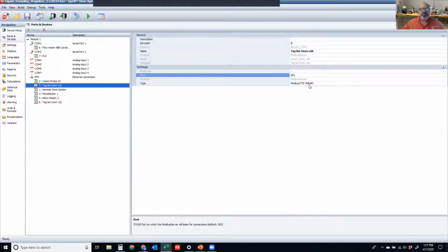So it's a way of creating multiple communication templates that are used within Ethernet and serial that allow the FlowX to look like other devices, or to create custom Modbus mapping, so you're not limited to having to use a standard template across the entire device. You can create large templates, you can create small templates, just a few registers. I don't need to create a template that's got access to 8,000 registers if the PLC is just going to pull me for 5 things: flow rate, temperature, pressure, density. So we can really stream these down.